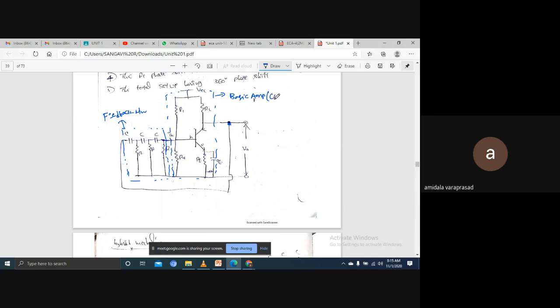That is the CE amplifier with a self-bias circuit. Now, this C and R, the RC, has a 60-degree phase shift. Here 60 degrees, here 60 degrees, here 60 degrees. Together, the three give us 180. And the amplifier gives 180, total 360 degrees.